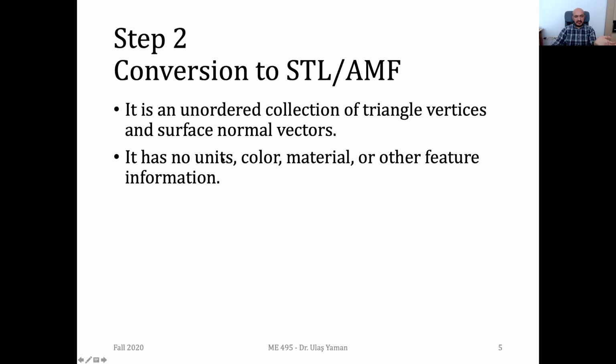Another thing, as I mentioned, we don't have any color information inside. We don't have material information, other feature information, tolerances. Nothing is stored in the STL files. Just the information about the triangles we have. And there are also no units. You don't have unit information, but most of the time, we assume that the unit is millimeters. If you want to have a unit in inches or meters, then you should do some modifications in your CAD software or in other manufacturing software.